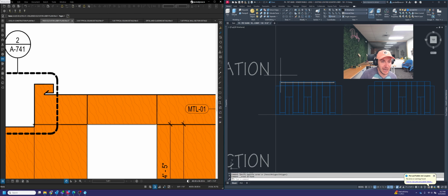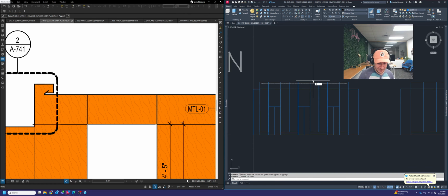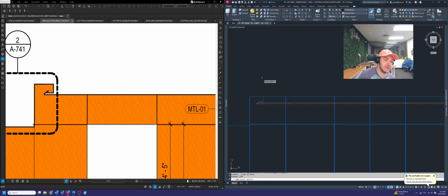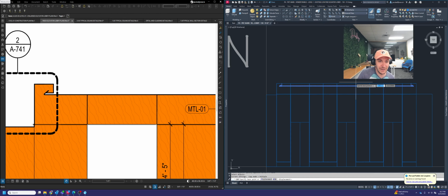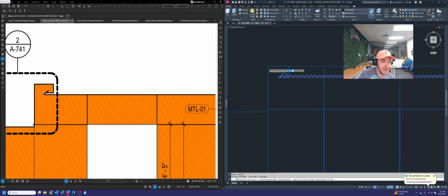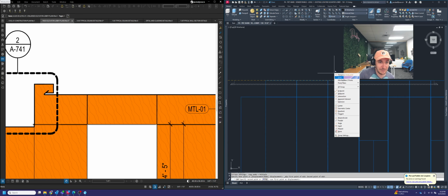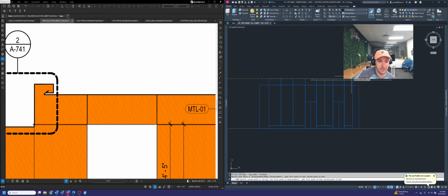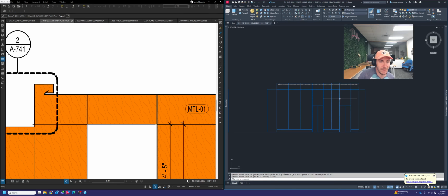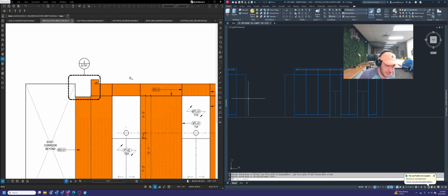But I do need to copy these gray lines from this elevator lobby elevation to this elevator lobby elevation. And our elevator lobby should not have changed in width here. Because of that, I can actually find the midpoint here and copy and paste that over there. So I'm going to go shift right click, mid between 2 points, and go from far front to far back of my elevator lobby, and then do the same thing over here. So from far front to far back of my elevator lobby, and that should do a very good job of representing the ceiling in this room.